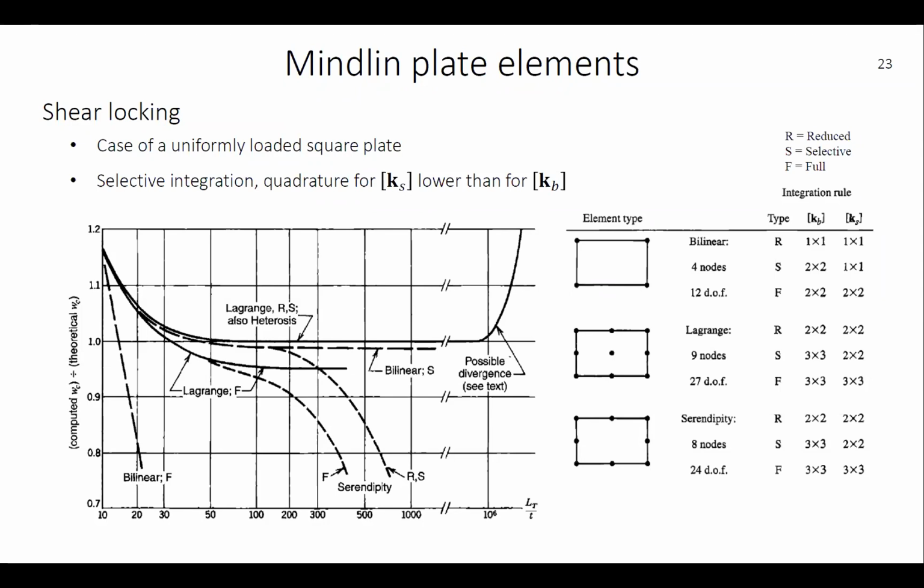So that's quite important when you use any commercial software, that you know what kind of element formulation you are using. I will show that a little bit, how that is defined in Abaqus and where you find the different elements, because part of exercise A is for you to compare different element formulations with each other.